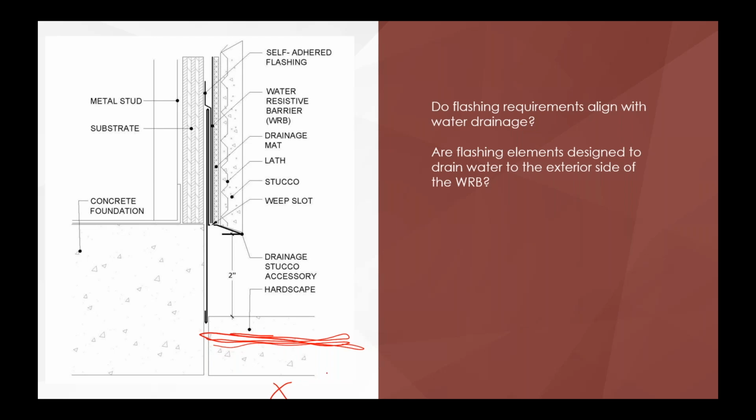What would happen typically is you'd have your waterproofer come out here, plywood down below the topping, and they would take that waterproofing all the way up here. And then I've got my topping on there. And right here, this 2 inches, this is by code, the stucco has got to start 2 inches above hardscape. What would happen a lot of times is that in this area right here, the waterproofing would be exposed. Well, the thing about that waterproofing is it doesn't have any UV protection. So over time, it would get wet, get hot, and eventually it would blister. And when it blistered, water could then get behind the waterproofing. Now it's behind the waterproofing, and it's going to get down into your plywood or whatever your framing is down here.